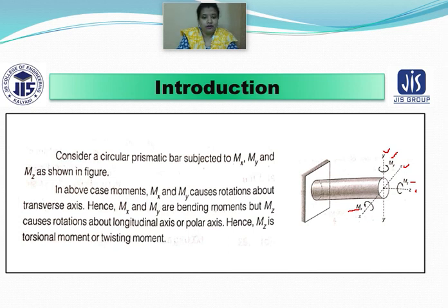But for other shapes or split sections, it can be much less, and for more accuracy, finite element analysis, that is FEA, is the best method to calculate it. Other methods to calculate the torsional constant include the membrane analogy and shear flow approximation.